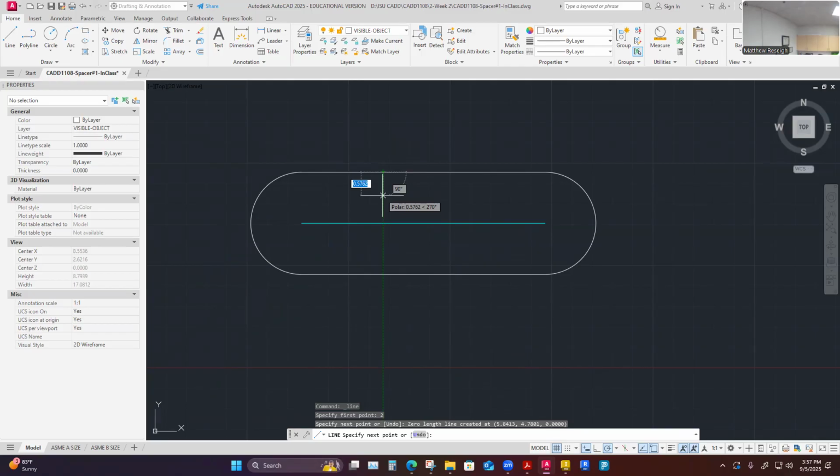But in how people use ortho mode, they would toggle on ortho mode. If I hit F8, I'm going to pull this slightly crooked. If I hit F8, it binds me to being straight up and down here. I can only draw vertical or horizontal. So that allows me to not make a mistake in pulling something slightly askew. So 0.5 is how far this needs to go down. Perfect. So I entered and clicked there.